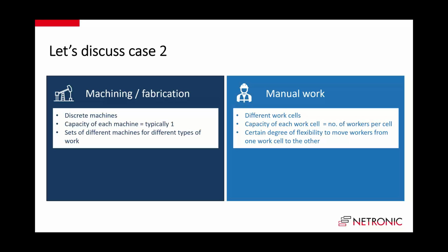They say, I typically have 8 welders and 5 people in this assembly line, but sometimes one of the welders might be idle, and then I can send him to help out with a large assembly job, moving them for the next week from one work cell to the other, so that I can level out excess capacity requirements in one work cell.